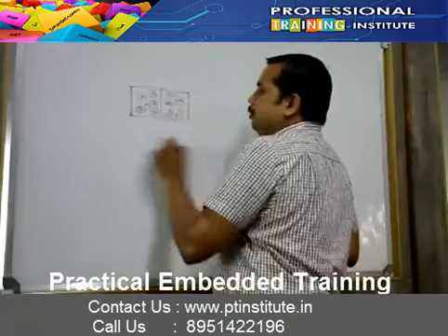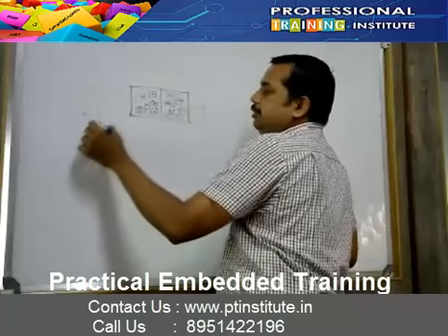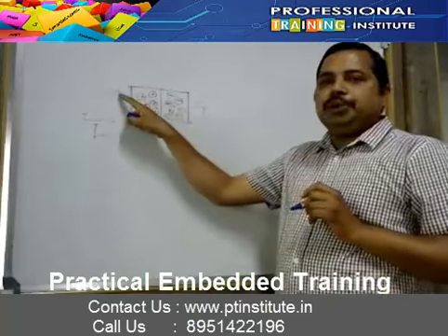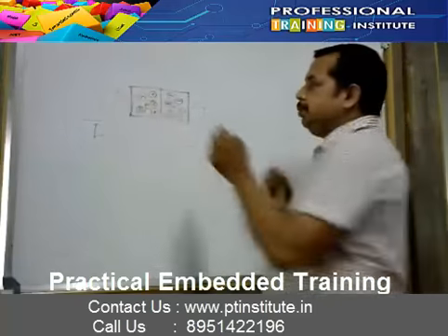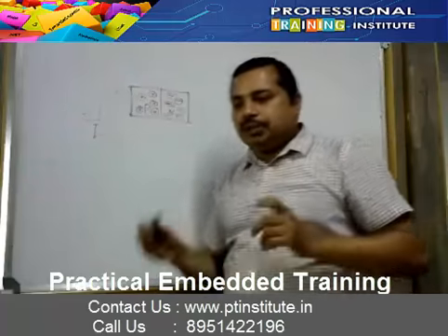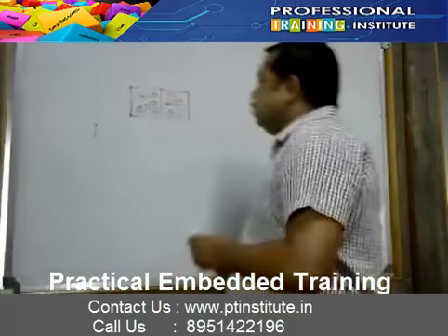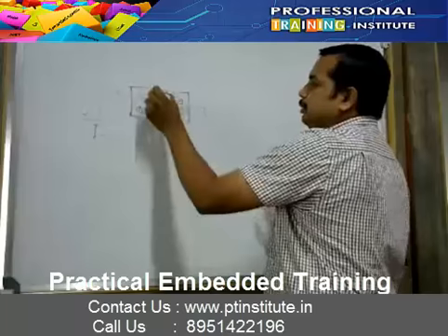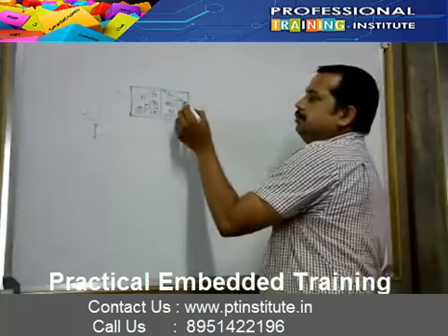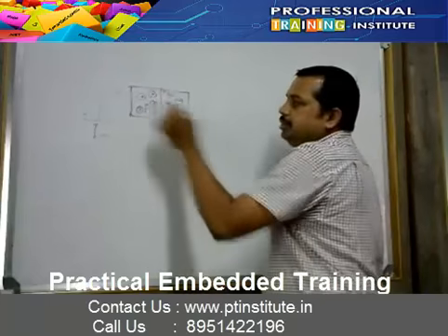So now we apply a voltage: positive here, negative here. When we apply positive voltage here, what will happen? It starts repelling the holes, so the holes move in this direction. At the same time, the electrons are repelled by the negative charge and start moving in this direction.